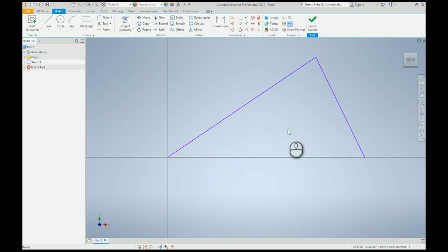We design the mechanism exactly when the crank pin enters the slot on the Geneva wheel. At this moment the crank arm is perpendicular to the slot. So this angle will always be 90 degrees.